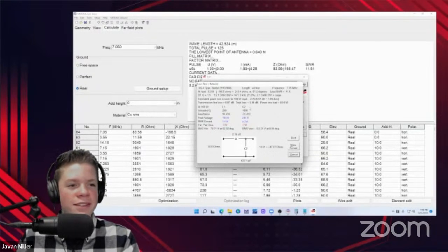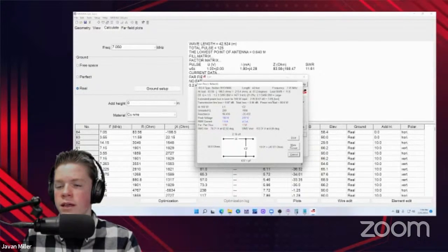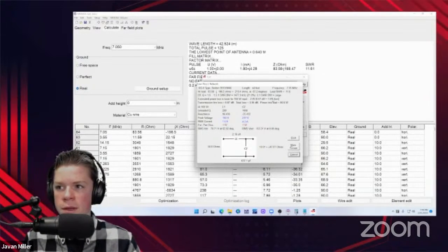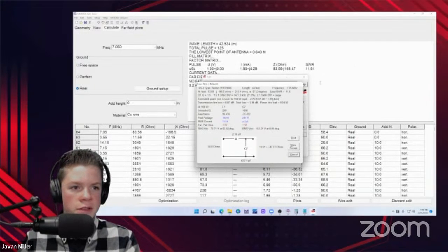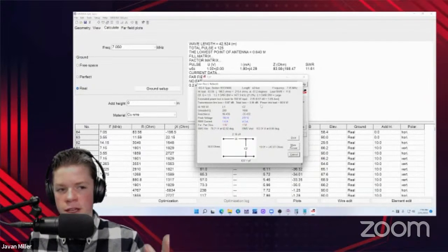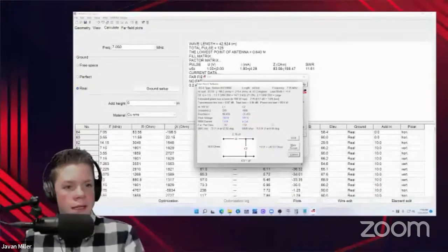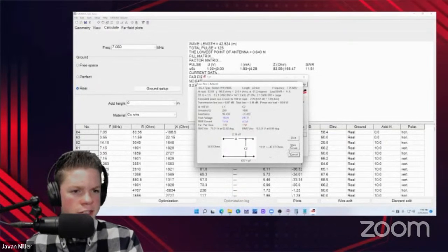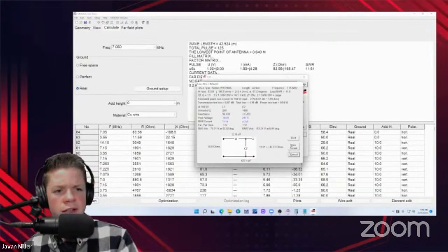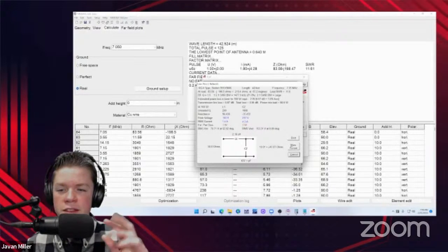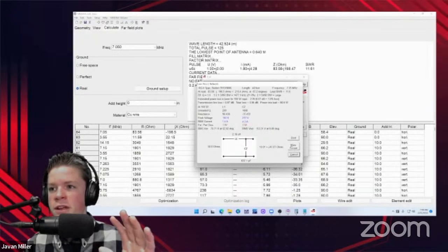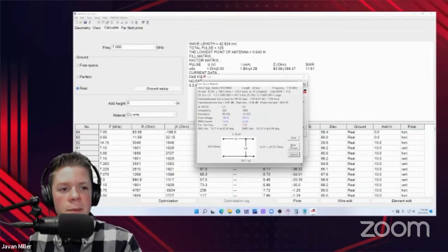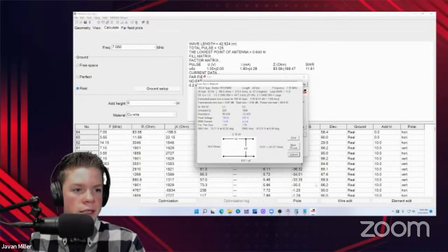All right, so here on 40, it's not too bad. Again, at this frequency, we're not going to see a lot of coax loss for a high SWR mismatch. You can see a total of about 1 dB in loss, which is pretty much nothing. Except for the capacitor I see in the matching circuit, it's 637 picofarads. Again, this is just a test. I'm not sure what your tuner is like and what components it has, but that's what it would be like hypothetically in this situation.